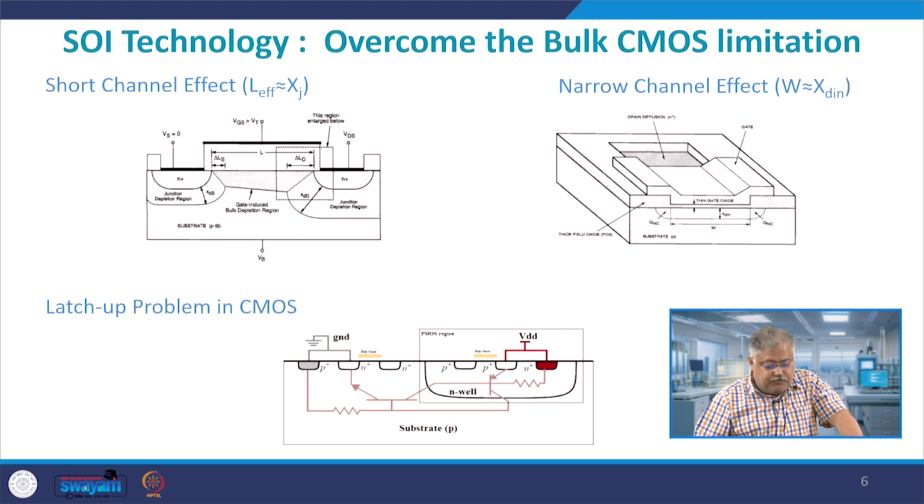Obviously, a large number of complicated circuits are being generated, and therefore you do not want the active part of the device to talk with the substrate to a larger extent, in order to reduce the parasitic effect and the off current. The reason is that you have a diffused source drain at the substrate. So, that is the reason it is better.